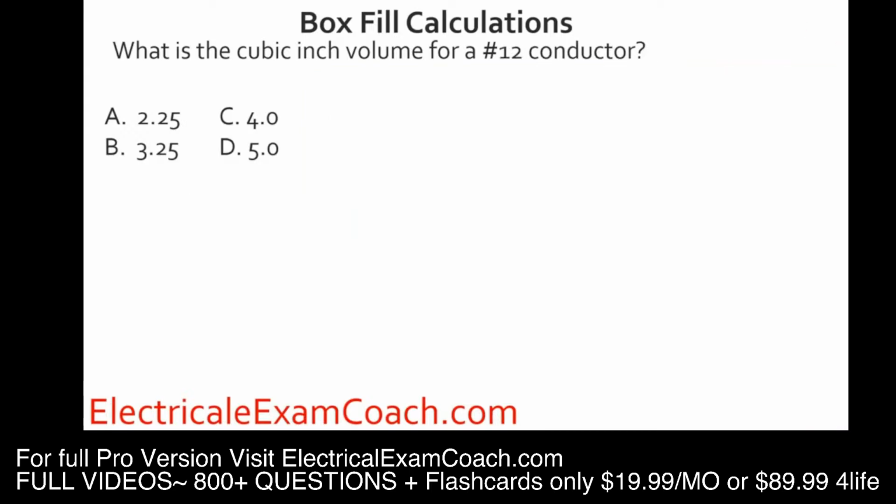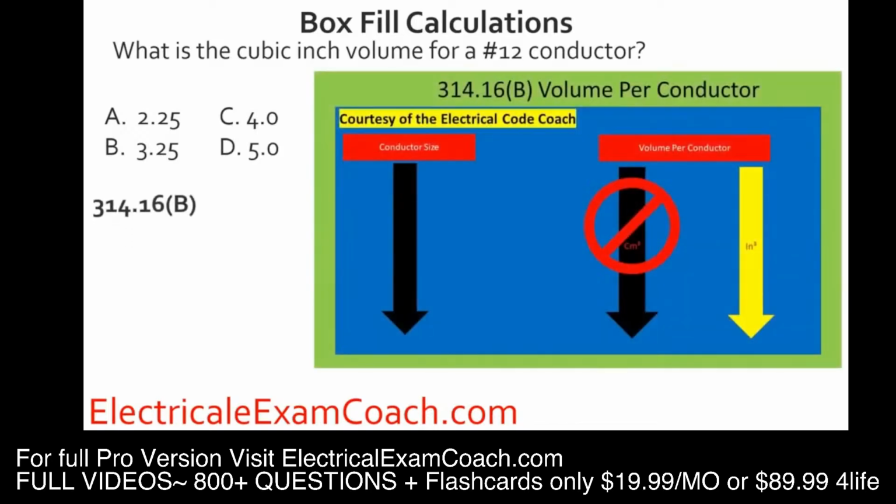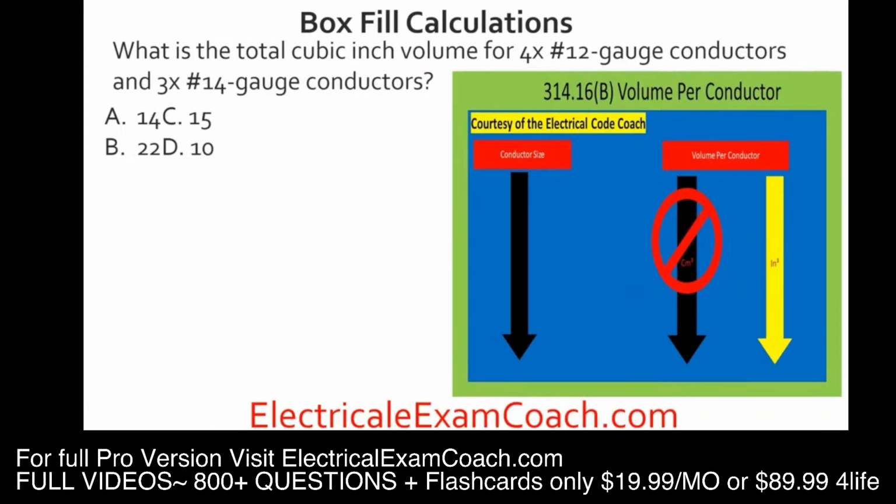What is the cubic inch volume for a number 12 conductor? Head back to 314.16(B), start on the left-hand side and find our size conductor, then cross over to the cubic inch volume, and it's stating that every number 12 that's in that box, according to the count, which we're getting ready to learn, takes up 2.25 cubic inches of that box. Let's get to it.